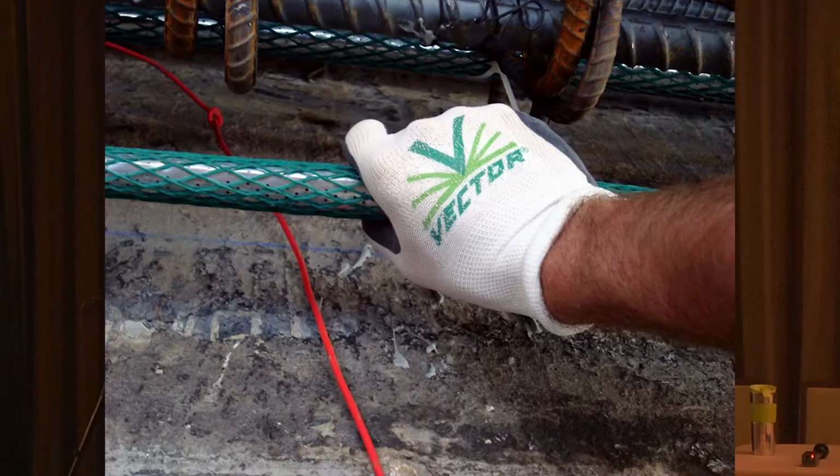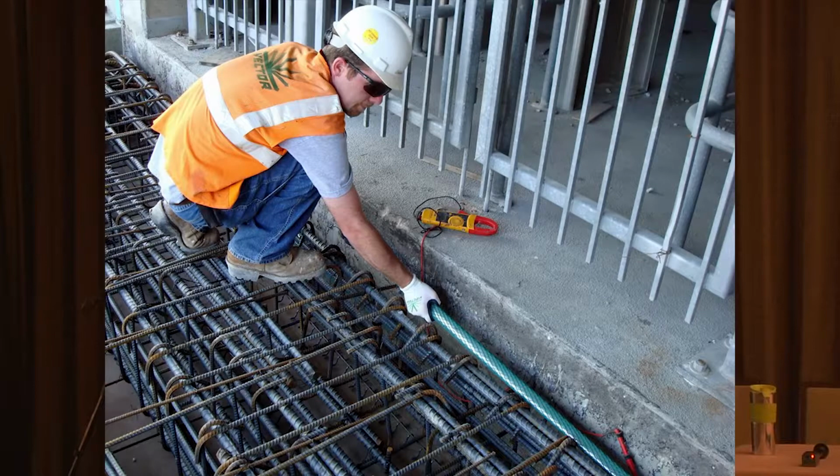This is what it looks like. Basically, in this particular system you have a tubular anode, and here you can see it going in. These come in versions anywhere from 6 inches in length to as much as 6.5 feet. It has a solid core of zinc surrounded by that activating mortar with a zinc foil, and then a mesh on the outside for handling purposes. In this particular case, it's being installed at the interface between a chloride-contaminated area and some new concrete that's going in. It will be protecting the steel in this area with new concrete.